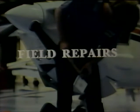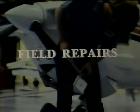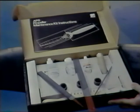Small nicks in propeller blades may be repaired by the technician in the field. Extreme caution should be observed to assure an airworthy repair. Before attempting a repair, the proper equipment should be assembled. These tools may be gathered from stock sources or purchased in a kit like the one seen here. Either way, the files and other tools used for a propeller repair should not be used for any other job.